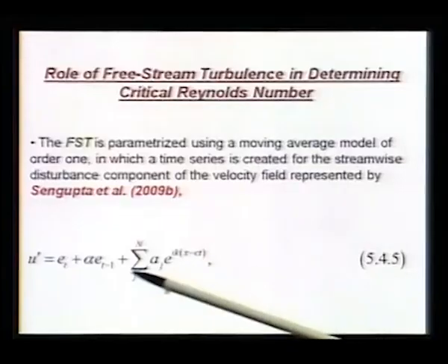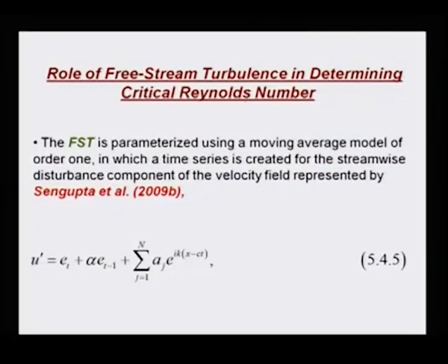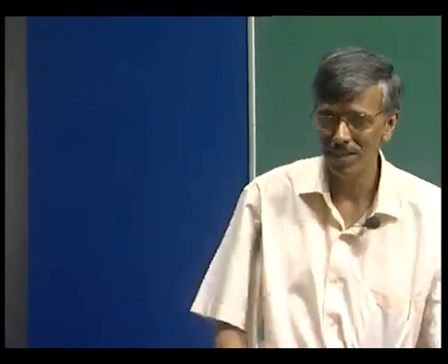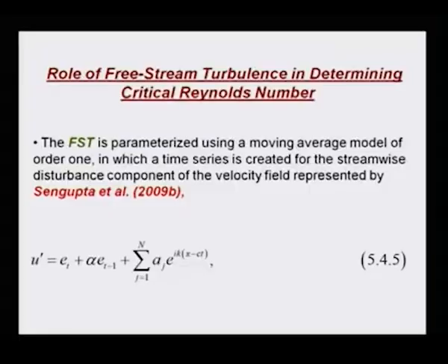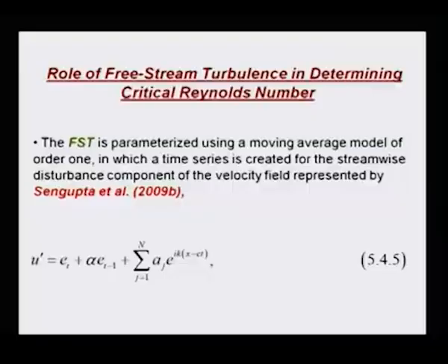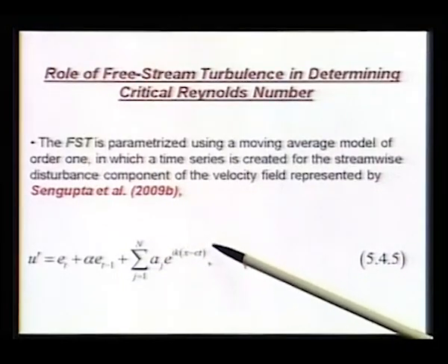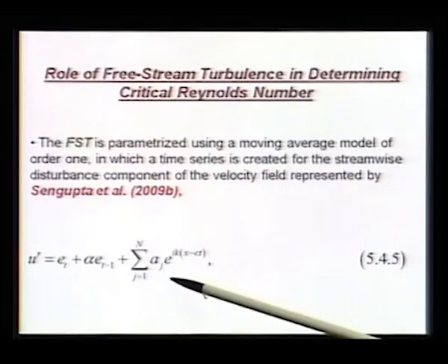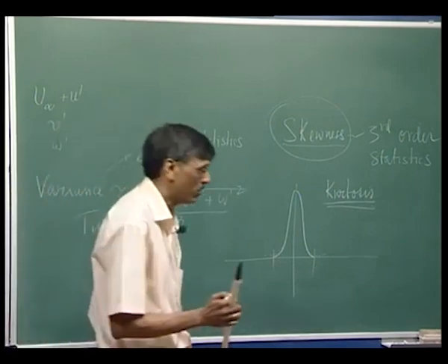Because these are constituted by normal distribution, a combination of the two will always give you even moments only. So, with the help of that, we could fix the second order statistics and the fourth order statistics, and the deterministic event of the tunnel itself would be explicitly kept. That corresponds to basically the skewness. So, that was the whole idea of generating this particular turbulence model.